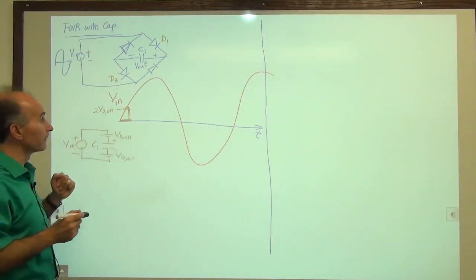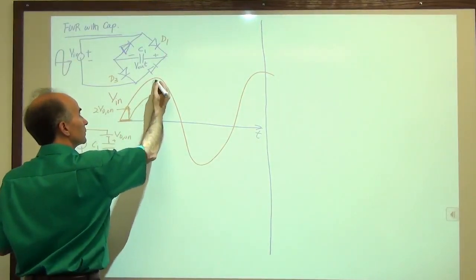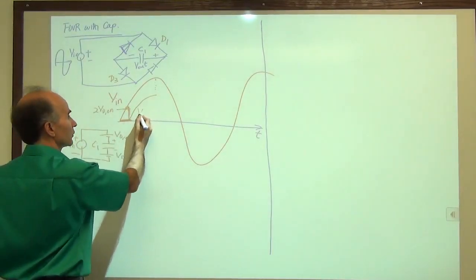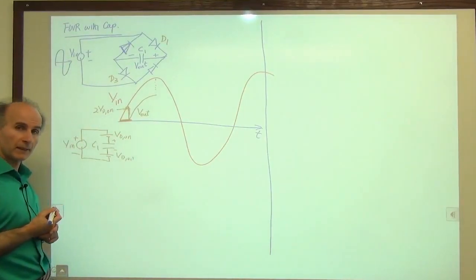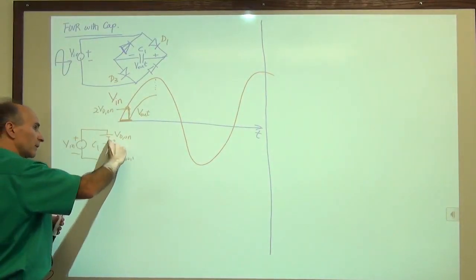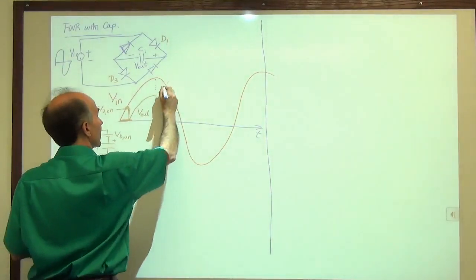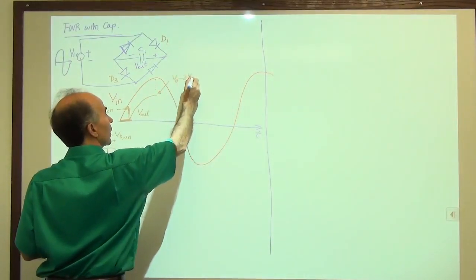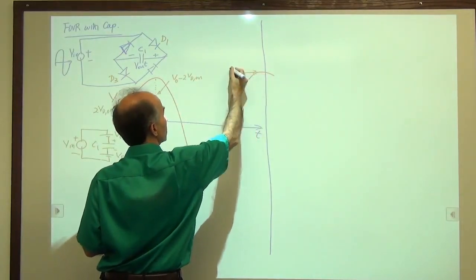This is what we saw before. So the voltage will start tracking the input all the way to the peak. So this is the output waveform. How much is the peak at the output? Well, again, remember that when we wrote the KVL, we saw that this output tracks the input minus 2 diode drops. So what we have here at this peak is V0 minus 2 VD on, V0 indicating this peak value here. So this is V0.